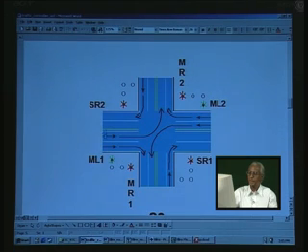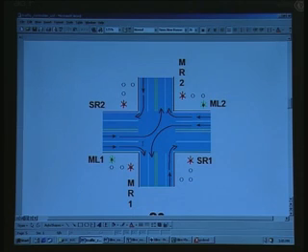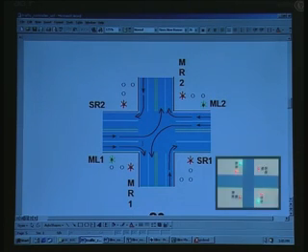For example, let us say earlier there was straight flowing traffic here, going this way, and we have said that straight flowing traffic is timed for 45 seconds and another 5 seconds for the yellow transition. So that would take 50 seconds, and for left flowing traffic, even from main road to side road, we have given a timing of 20 seconds plus 5 seconds for the yellow. So in total you have 50 plus 25, 75 seconds, and you will have to wait if you are on